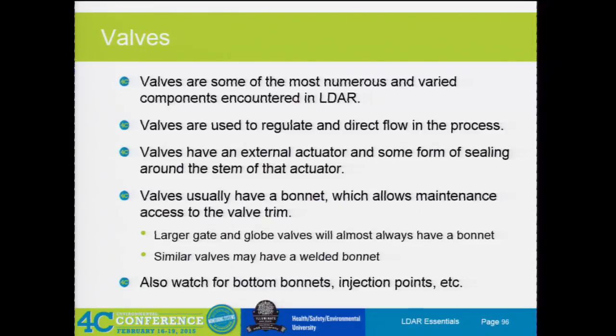Most of them have a bonnet. Sometimes you'll see a welded bonnet. And we talked about those earlier with the monitoring pyramid and how it takes less time to monitor. The thing to watch for is little plugs on the bottom or injection points from a previous drill and tap. All those are new potential leak interfaces that they could add to a valve, making more monitoring for a technician. They're readily missed as well.